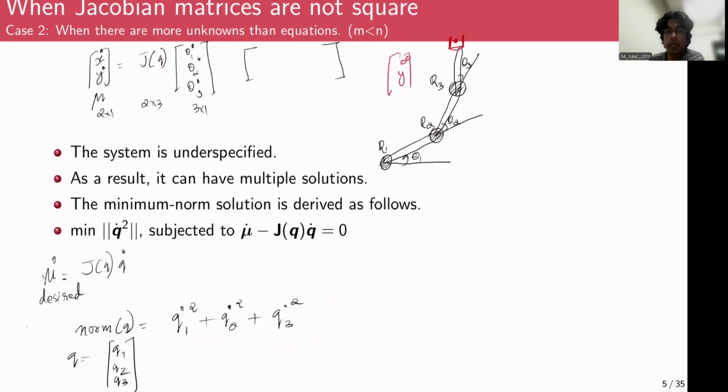We do so in robotic manipulators. The reason we do this in robotic manipulators is that the kinetic energy, or the energy spent, is actually proportional to the square of the velocities, half mv square. The energy spent is proportional to the square of the velocities of the joint variables.